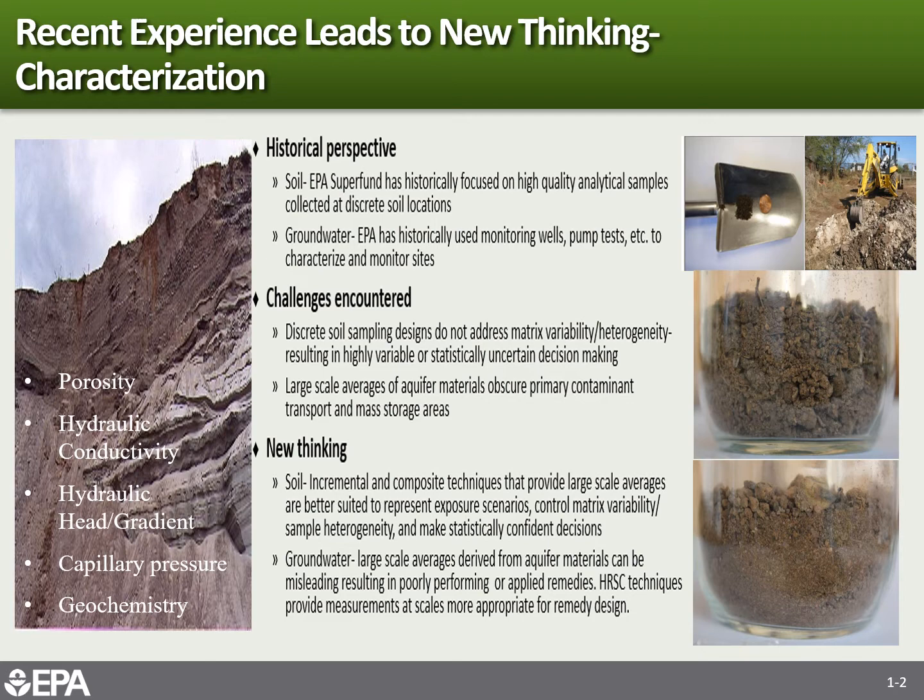In fact, here's an example of a jar where we placed a soil sample and jiggled it down the road in a car for about 30 minutes to show what moving an unhomogenized soil sample in a truck can do to particle size. You see that all the fine particles, for example, fall to the bottom. And if you're in an analytical lab and you happen to take your gram of soil off the top, the metals analyses will be very different for those particle sizes than the ones that you might find at the bottom of the jar.